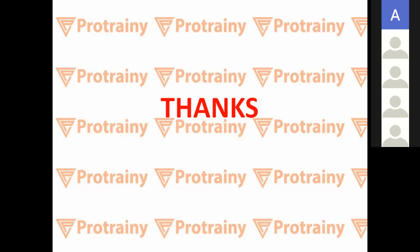So you have to divide your plan as per X and Y frames. Now can you tell me how many bays there are in your plan? Rows of columns along the X axis and along the Y axis. Along the X axis 4. Okay, so if there are 4 columns, then there are 3 bays, and along the Y axis 5. So there are 4 bays.